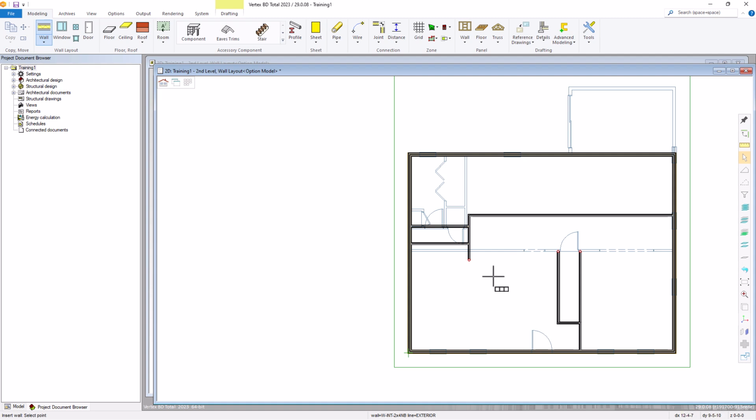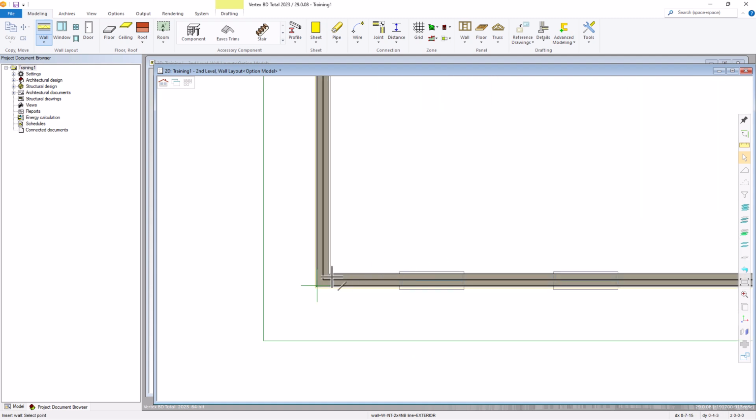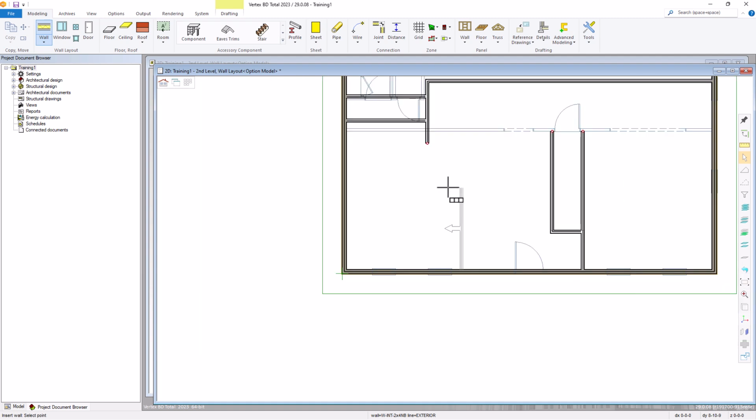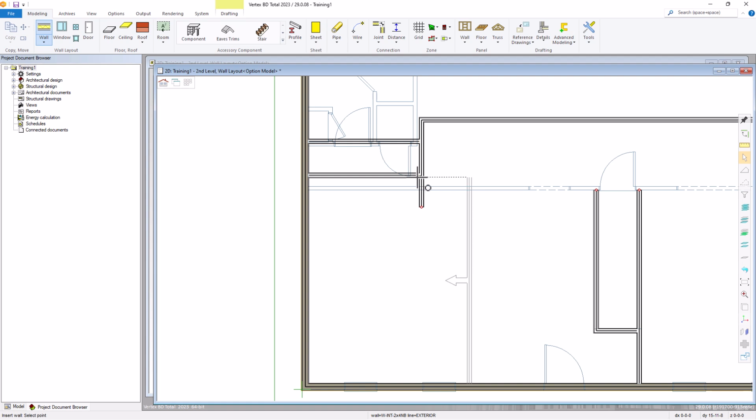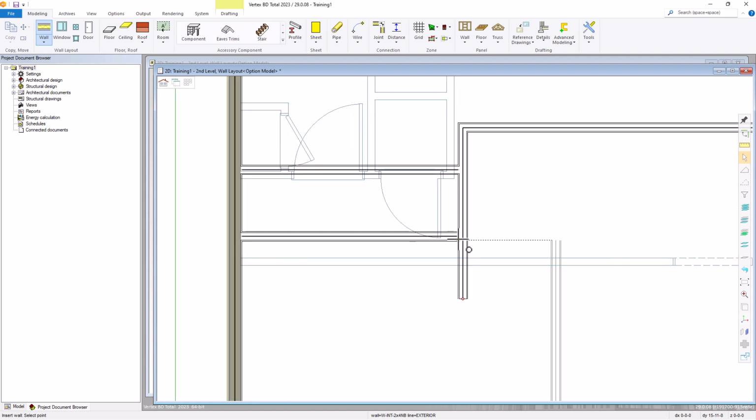Next we have a vertical wall that is 12 foot 1.5 inches over. So we'll zoom in, go to this interior corner, hit Q, hit the letter U for the horizontal constraint, and type in 12 foot 1.5, or you can go 12 foot 1.5. Either one will work. Hit the letter I to lock it in the y-axis, and this wall offsets to the right. Go up to this wall here. It's just going to butt up against this wall, even though they're not touching. We'll clean it up later. So V to confirm.